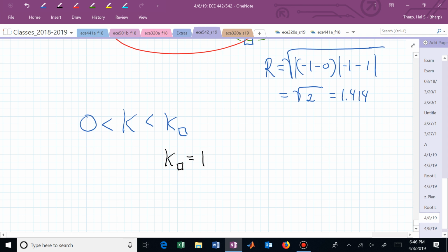But what do we know is happening in the steady state accuracy? If I put in a 3 for a reference, what's y going to go to? It's going to go to 3 because we had a pole at z equal to 1. We forced 0 steady state error due to a constant because of the PI controller. We'll pick up at that point after the exam with PID controllers, etc. But that's enough for now.